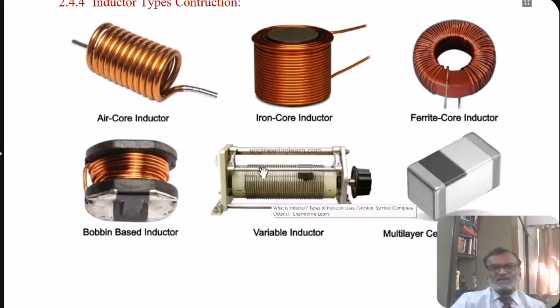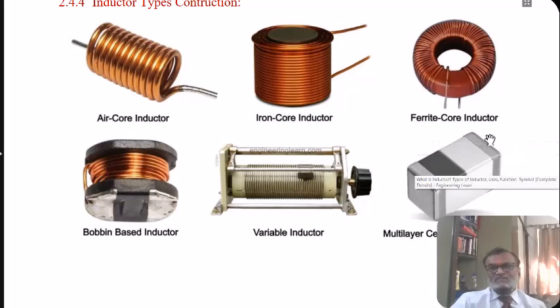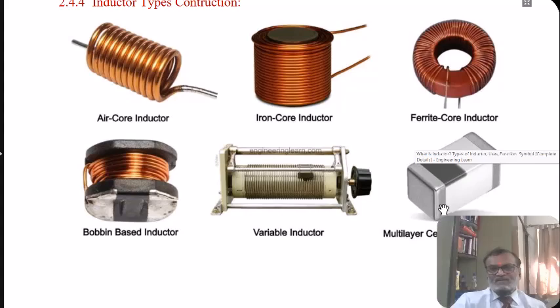This is a highly conducting wire instead of a resistance wire, and the number of turns of this conducting wire between the fixed terminal and the wiper decides the inductance between fixed terminal and wiper. Whereas a ceramic chip inductor is shown in this figure, in which the multi-layer inductor is manufactured and enclosed in the ceramic enclosure.